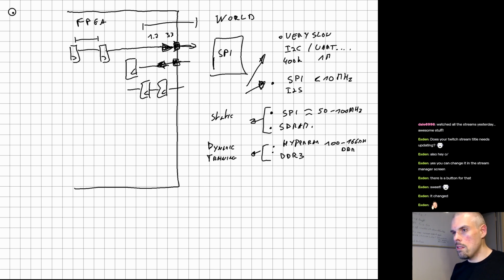So what that means is that at boot up, your FPGA or your PC, like the DDR on your PC, doesn't actually know the various IO delays on the board and between the CPU and the RAM. It dynamically tries different delays and tries to find one that works. It's a bit simplified, but that's essentially the idea. That's what's called memory training for DDR and stuff like that.